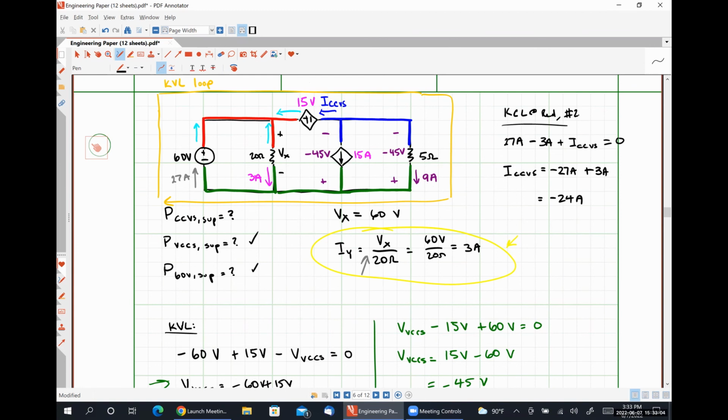So for these KCL expressions here in particular, where I'm not using Ohm's law or anything like that, I'm literally just comparing the direction of the current that I have solved for to the direction of the current that I quote unquote want based on the formulation of KCL that I'm applying, right? So for KCL version number 2, where we are saying all of the currents that are entering the node equal 0, I just drew all of these light blue arrows as if they were entering, and then I compared the currents flowing through those branches to the direction that's indicated by the arrow.